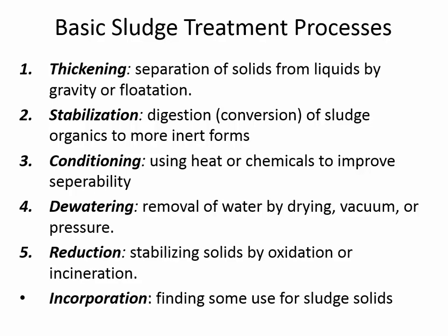Reduction is becoming less common because in the past sometimes they would just burn the sludge and allow the sludge solids to burn away, and the water component in the sludge, of course, will just evaporate. But it uses a lot of energy if you're burning something that's 98% water. And the other problem with it is if sludge has heavy metals, then you're putting mercury and lead up into the atmosphere. And so instead of doing these things too much, what we'd really like to do is find some way to recover the nutrients like phosphorus and nitrogen and incorporate the sludge into some beneficial use.